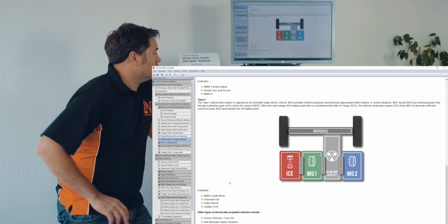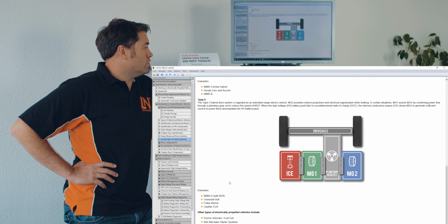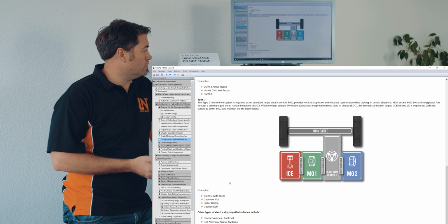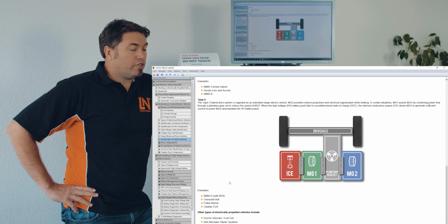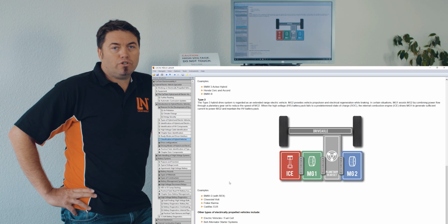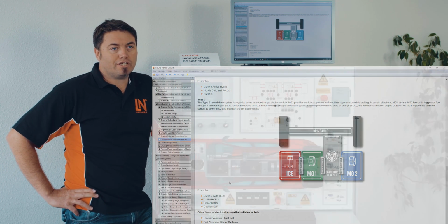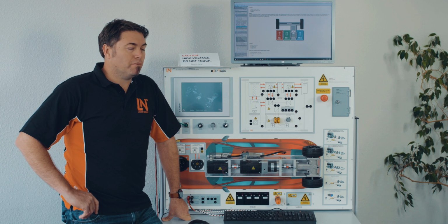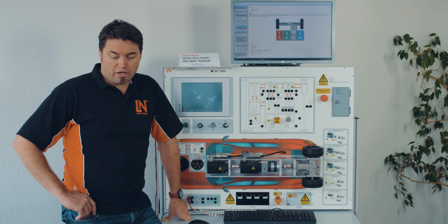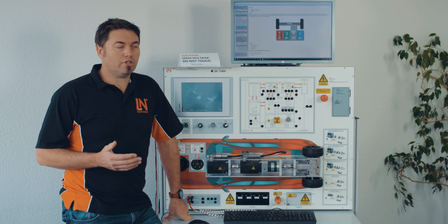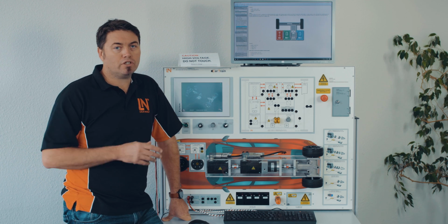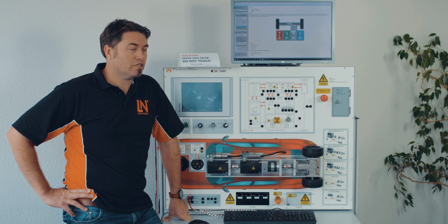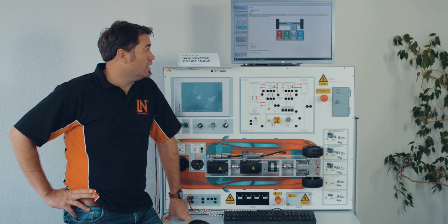You've also got fuel cell type vehicles, obviously pure electric vehicles. Belt alternator starter systems are also included as a micro hybrid, some people like to call them. Sometimes they're running 48 volts. Now that doesn't use the orange cables like you do on a hybrid vehicle. You often see the yellow cables for that, sometimes blue cables.